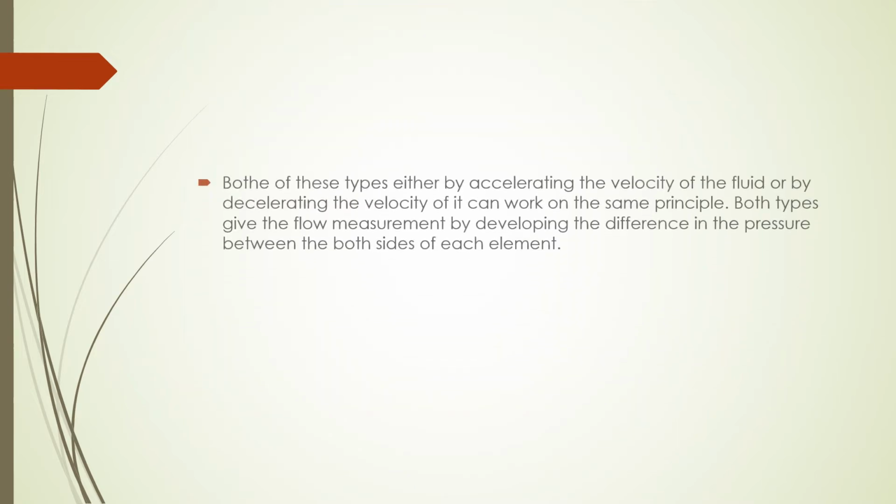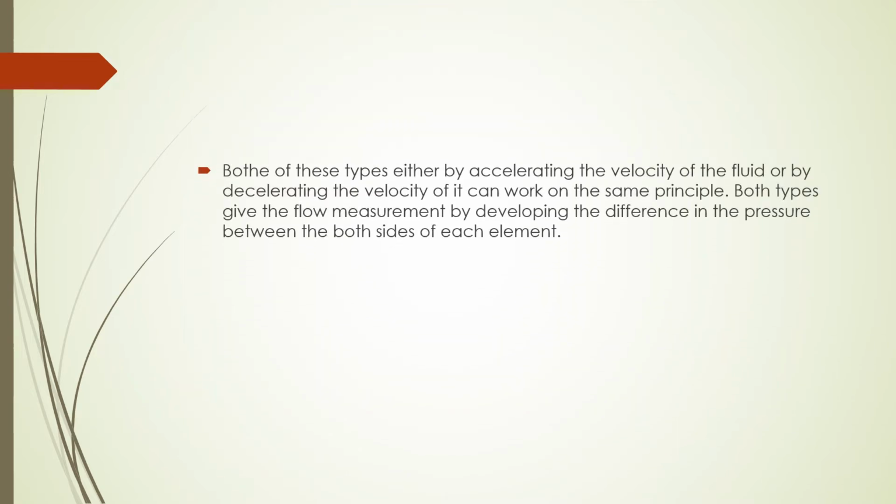And note that all these differential pressure elements work either by accelerating the velocity of the fluid or by decelerating the velocity. It can work on the same principle. Both types give the flow measurement by developing the difference in the pressure between both sides of each element.